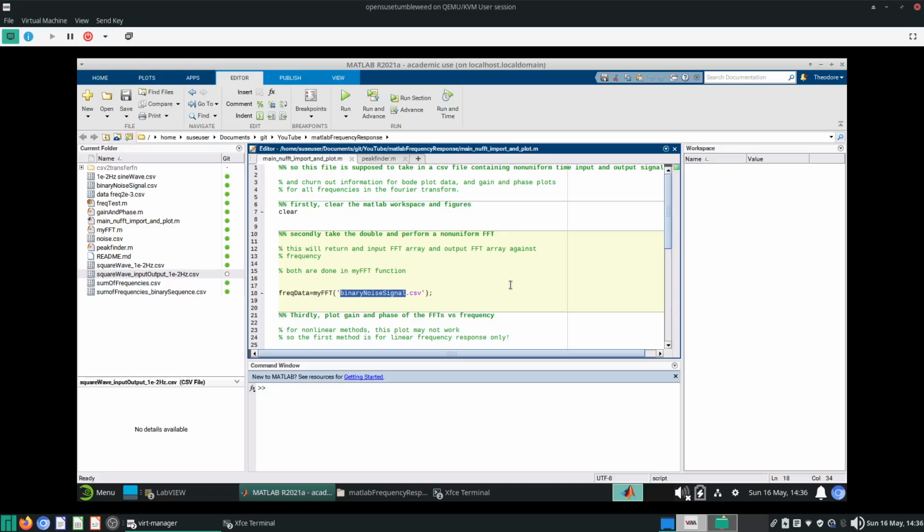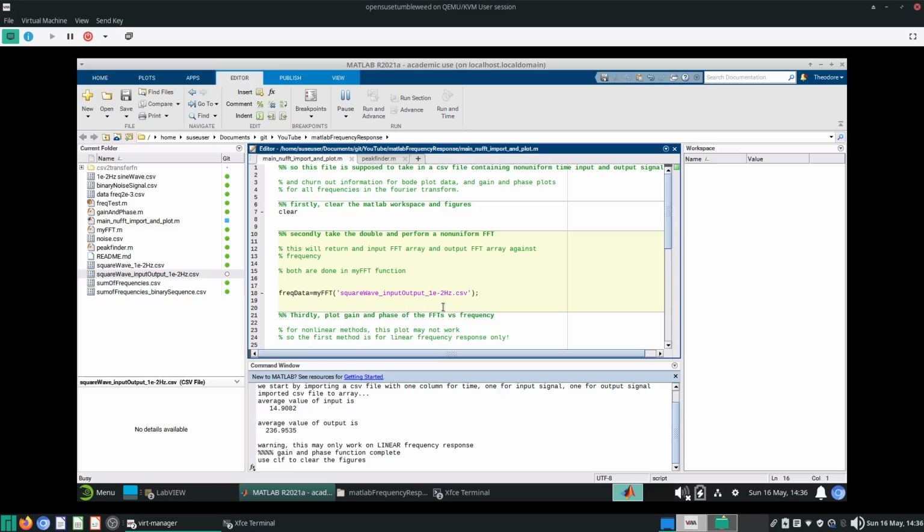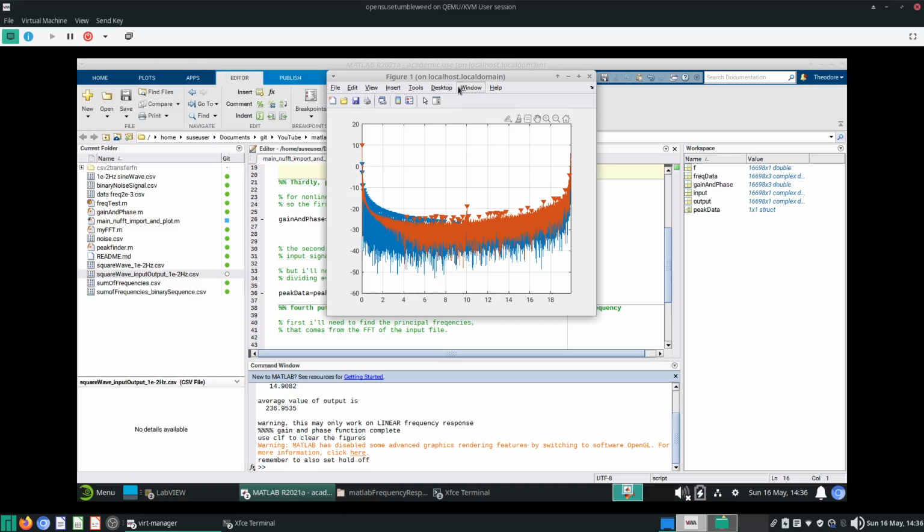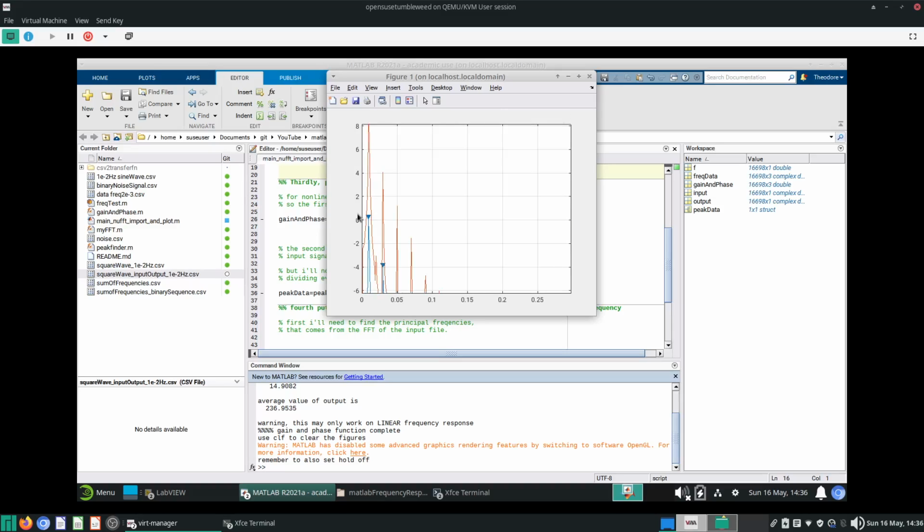It's kind of redundant, but it works. Okay, so I'm going to put it to a fast Fourier transform. I'm going to compare input and output, of course subtracting the DC gain. So I put it in log plots again, actually. So a lot of this will be noise. But we can actually look at the two strongest signals.